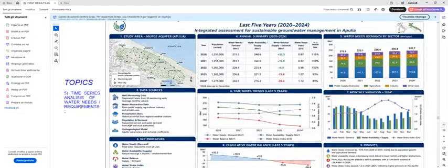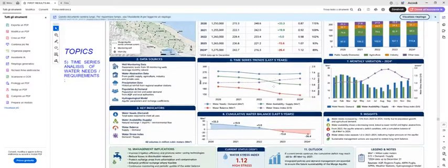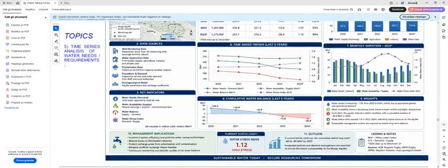The divergence of the index means that the aquifer started to be stressed, because the requirement was much more than the water availability where it was extracted. And finally you have a cumulative water balance in the last 5 years.